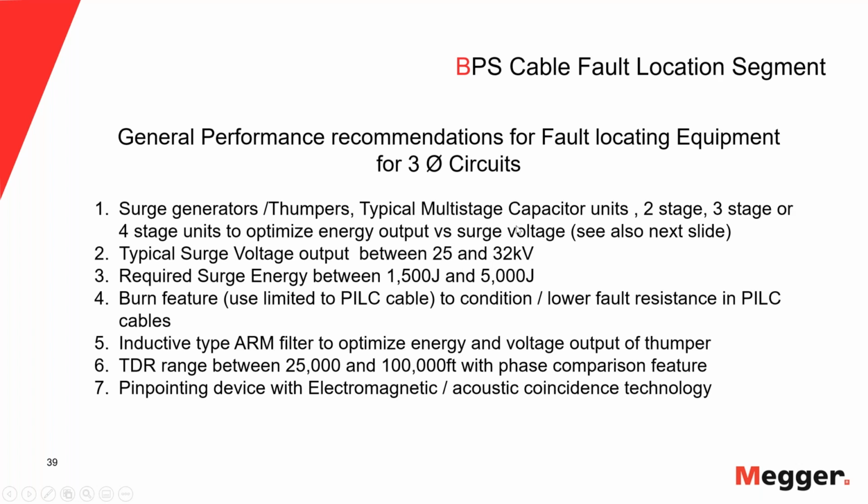20 kV, that is not a plastic cable. That is not a solid dielectric cable. That is in the paper section. So if I know it's in the paper section, then I can also much more freely use a burn feature, because a burn will only occur at the fault location.